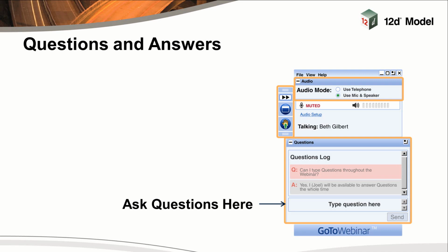Oh, you'd have to do one step first. So obviously, if it's a DWG file, you can either copy and paste that directly into 12D using the CAD copy paste, or import the DWG file, do any little cleanups that you want into the model, and then it's just one way into 12D. And once it's inside 12D, you can absolutely write that data out as a 12DA to the appropriate folder location. So yes, it's very, very quick to get existing details from CAD and export those to the 12DA library. There's just that interim step of getting it into 12D so you can write the 12DA file itself.